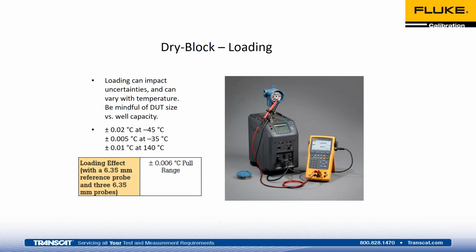Sometimes that can actually give you a little bit more of an error depending upon, again, size and stem length. So something to be aware of. If you do have a 1/2-inch stem on something, probably best to get a larger dry well versus a unit that can take that, but then you've got 6 inches of stem out, and then you're also overdriving or probably putting too much on the little block assembly there, the mass that's trying to control that. So again, just other little odd things that we've noted over the years.